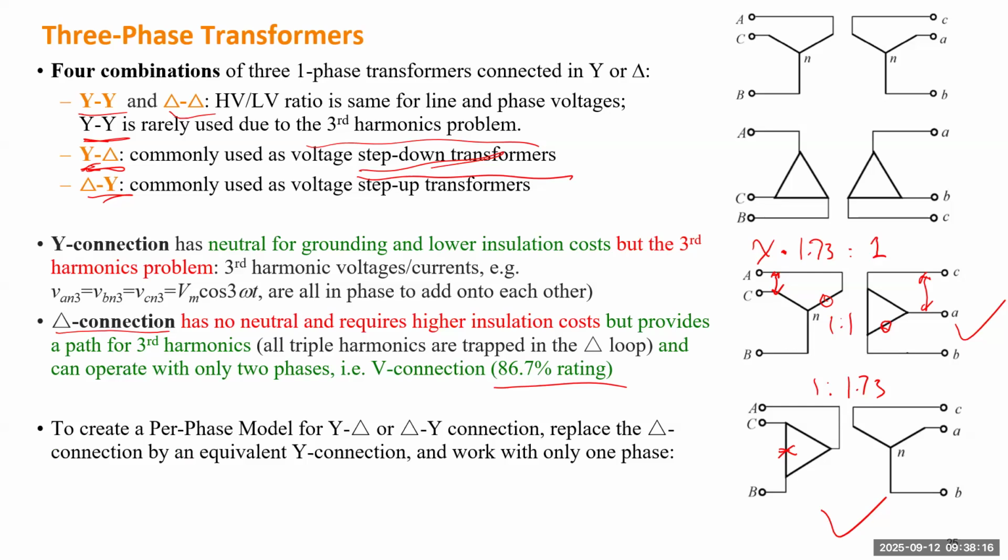So how are we going to do calculations for a three-phase transformer? The approach is to replace any delta connection by an equivalent Y connection. Once you replace every delta by Y, you only pick a single phase of the Y. Then you just do the calculation for a single-phase AC circuit. Because this course assumes steady-state conditions, a balanced three-phase system will be the assumption for any problem. So we can just calculate one phase, and duplicate the result for the other two phases.